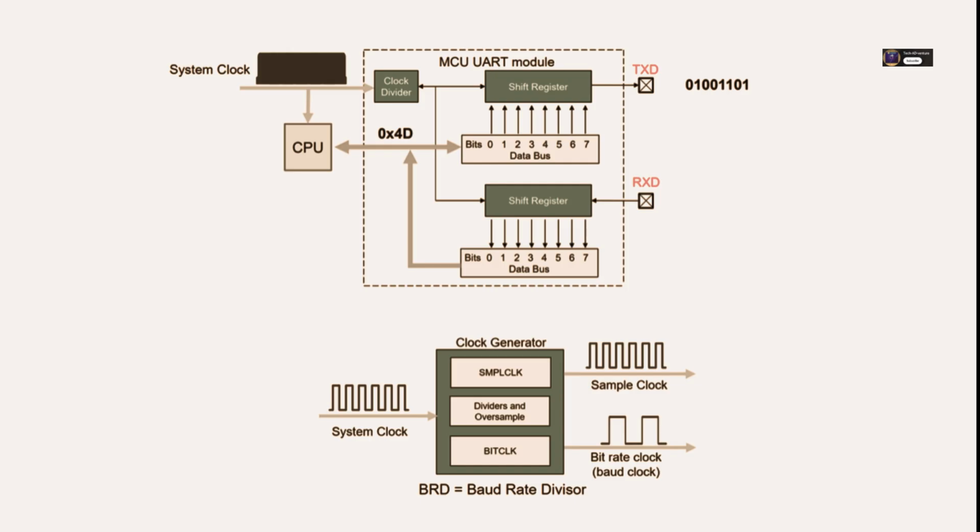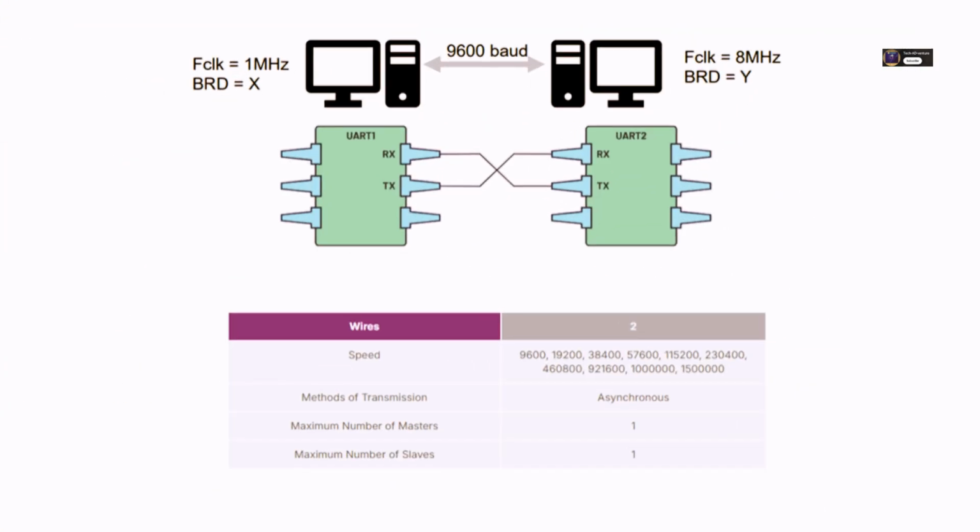Right. What happens if they're not? Say, one set to 9600 and the other accidentally to, like, 150, 200. Oh, you just get garbage. Complete nonsense. If the rates don't match, the receiver samples the incoming signal at the wrong moments in time. It misinterprets the bits. You'll see garbled characters on your terminal, maybe miss bytes entirely. It just won't work. Communication breaks down completely. It's like trying to listen to someone speaking way too fast or way too slow. You can't understand them. Matching baud rates is non-negotiable.